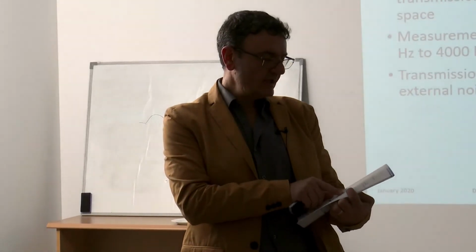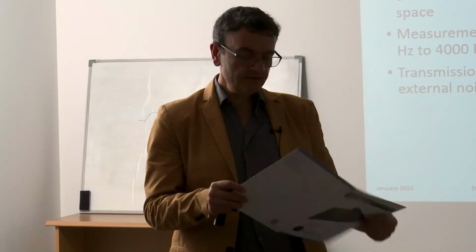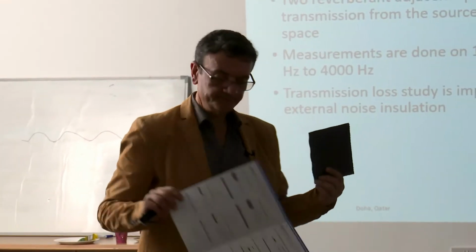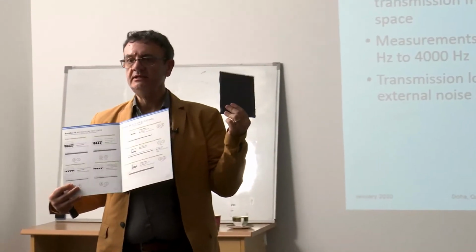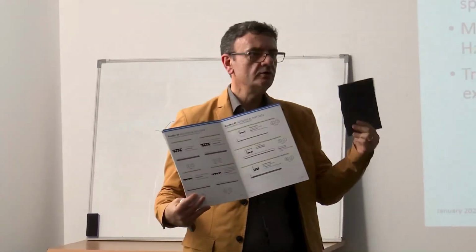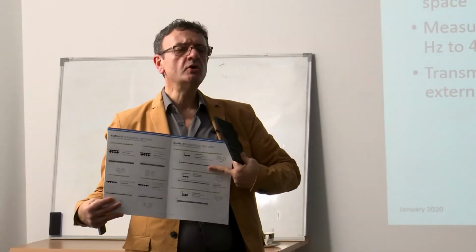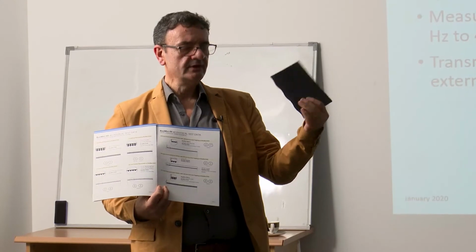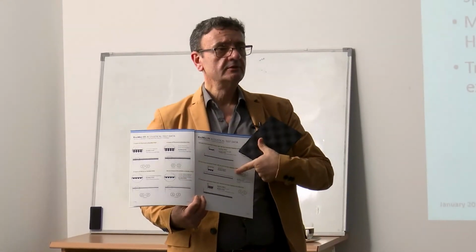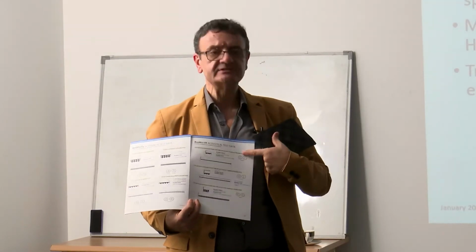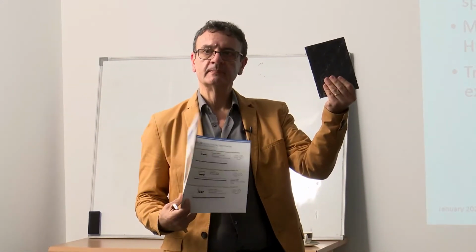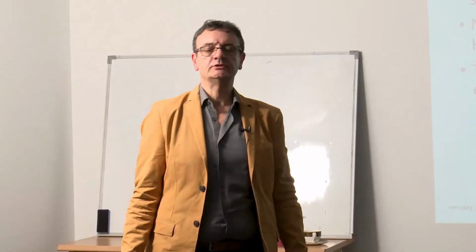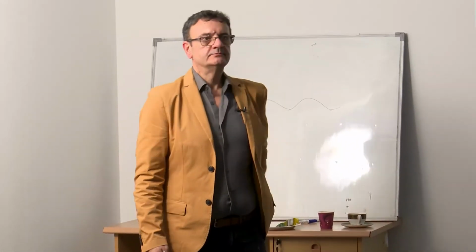Yes. So here you can see STC 59. And the STC 59, is it for this material? With the one we see here. Is it for this material? Yes? No. No. No. It is for this assembly. The whole system. And the whole system, including the material itself, is tested in the lab. Once you test it in the lab, you get an STC for the whole system, not for this. It is similar to FS1 doesn't have a fire rating. FS1 with the system, wall has got a fire rating. Absolutely. Exactly a similar method. STC is not for the material.